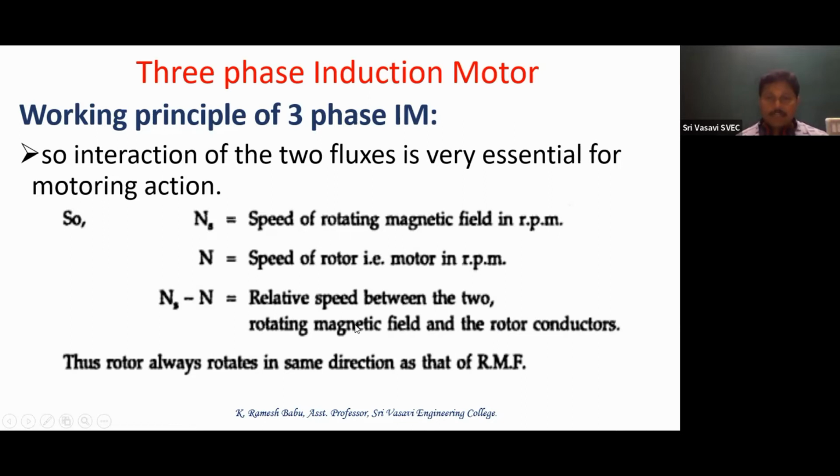Slip speed is the difference between the synchronous speed and the actual motor speed, that is, the relative speed between the rotating magnetic field and the rotor conductors. Thus the rotor always rotates in the same direction as the rotating magnetic field.